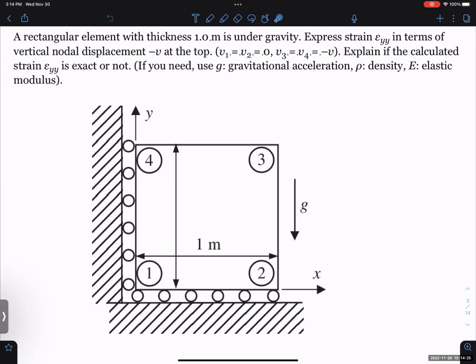So we can imagine that in this situation, the stress in the vertical direction due to body force is caused by the weight of the paper above the specific paper we are checking. From the bottom to the top, the weight linearly decreases. So the stress is weight over cross-section area.